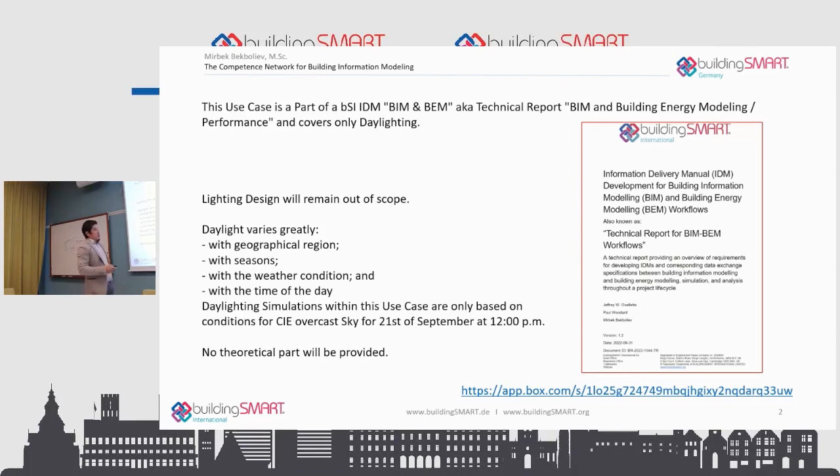Of course, within the document, we mentioned simulation aspects, simulation steps, and of course, if you start with conceptual design or bioclimatic design, you will in the end also simulate daylight analysis. So it's a really important aspect. Why? Because daylight has a very direct effect on your building energy performance or building energy loads that you will probably reduce if you plan properly, right?